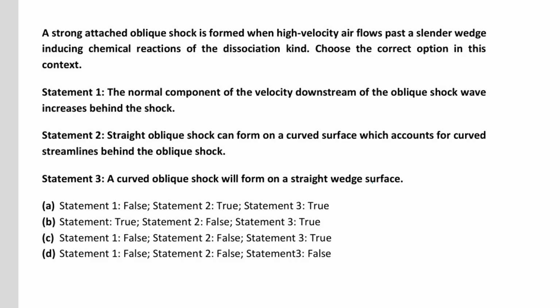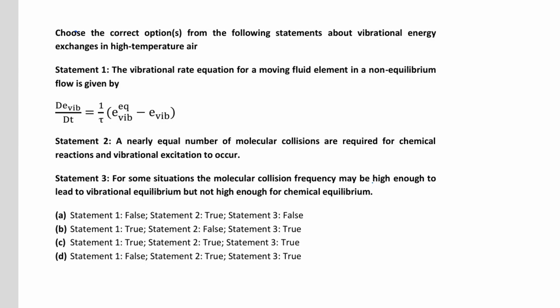Okay. First we will see statement 1, which says the vibrational rate equation for a moving fluid element in non-equilibrium flow is given by this equation. If you see this equation, this is the correct equation: dE_vibrational/dt equals 1 by tau times (E_vibrational equilibrium minus E_vibrational). So this is the true statement.